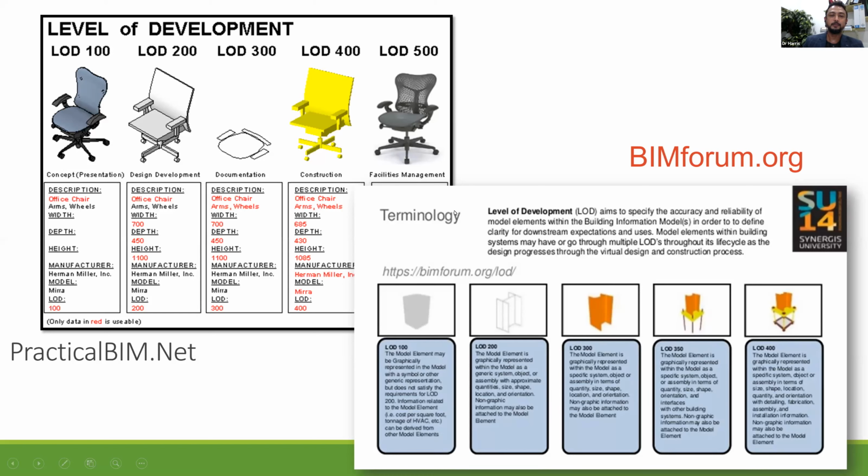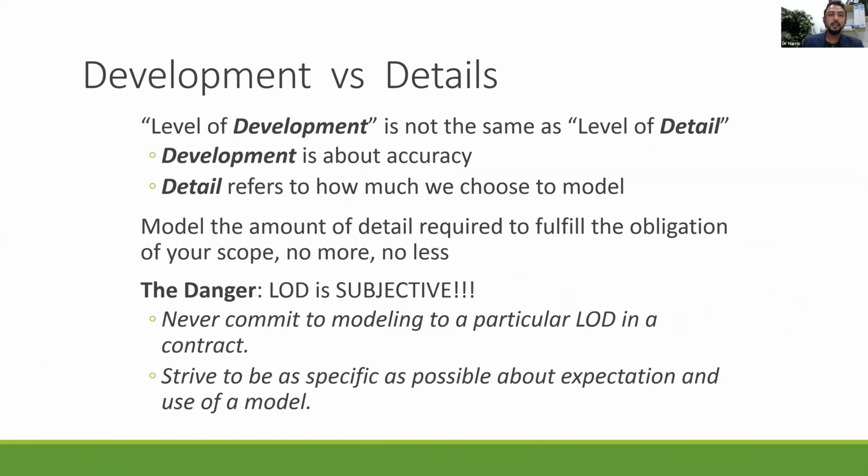You cannot mix up between all these definitions. And LOD, level of detail, and level of development are two different things. Development is about accuracy, detail is how much information that you input in the model. So LOD is very subjective. Now worldwide is going away from LOD.